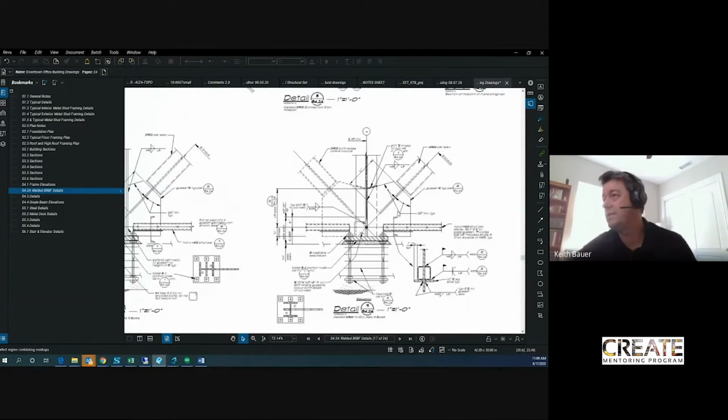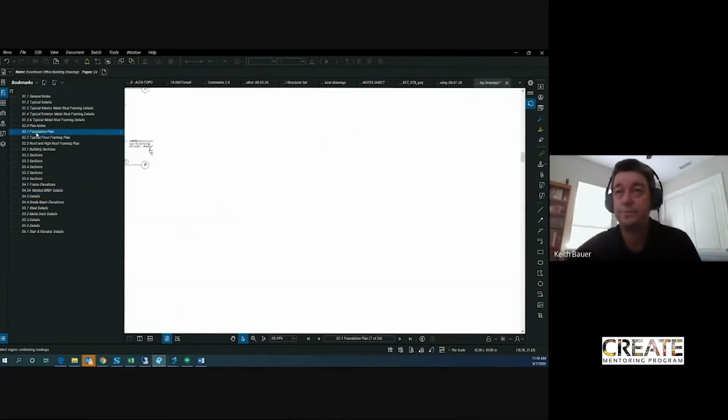Again, a lot more detail than you need to worry about right now, but it's kind of fun to look at. You see a base plate, the column comes down to the base plate, it's got anchor bolts that tie it to the footing, and then there's this plate that the brace attaches to, called the gusset plate, and it shows a bunch of information about the gusset plate. These little symbols, when you see triangles and flags like that, those are weld symbols, so it's talking about what kind of welds it means. And then it's calling out a bunch of other information too, in terms of the geometry, about the angle of the gusset plate and how they actually size it. So, interesting stuff. At least I think so.